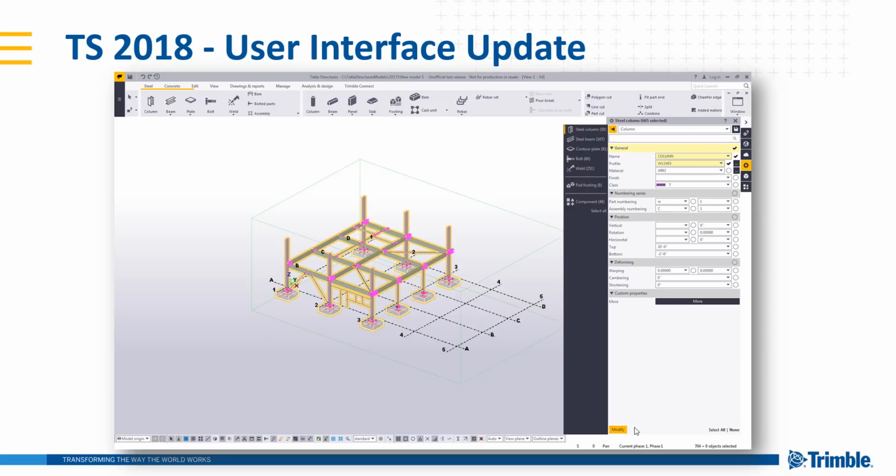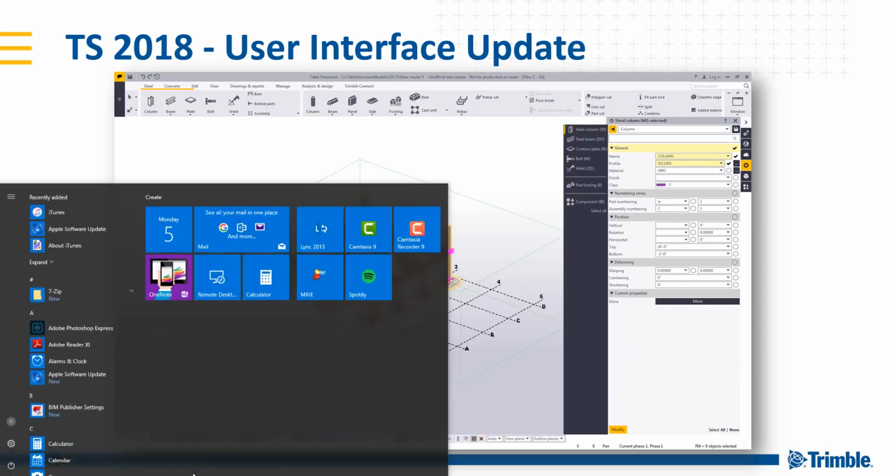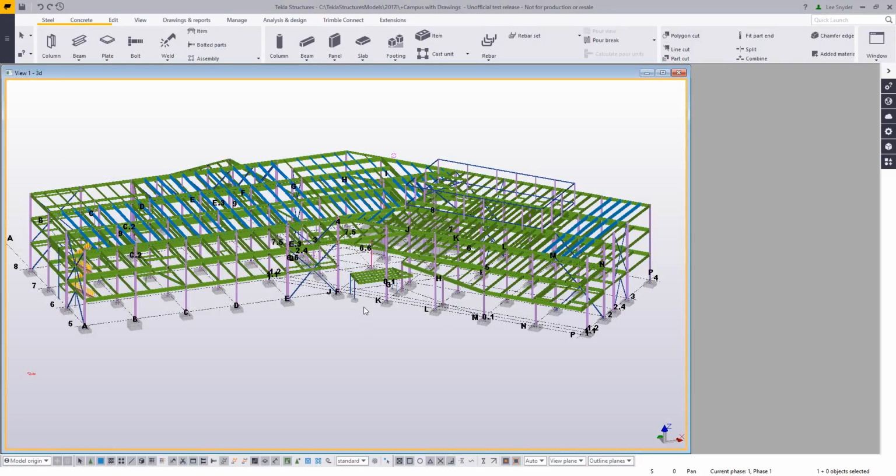Some of the other advantages is that we've removed the Get and Apply buttons here from the Property Pane that we used to have in the old dialog boxes. So that automatically happens now. So if I load in a saved attribute, those settings will automatically be applied. If I click on something in the model, this dialog box will automatically get those properties so that I can see those. And then if I need to change or modify those, then I can adjust those in the dialog box, and then I'll be able to click on Modify and see what's going to change about those parts and pieces.